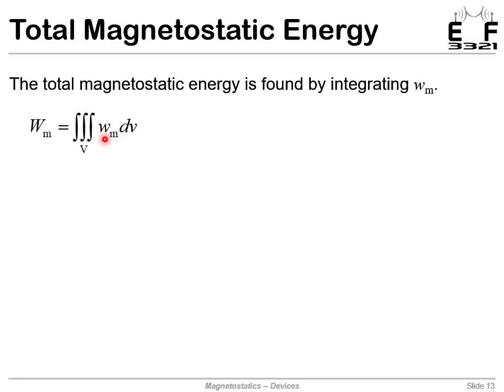So if we have this energy density, anytime we have a density term, there's an integral hiding behind it so that we can add it up and get the overall energy in this case. So we integrate the energy density to get the overall total energy stored in the inductor. And of course we have this handy expression to put in. We had 1/2 mu times H squared. So we bring the 1/2 to the outside and we just end up with mu H squared inside our volume integral.